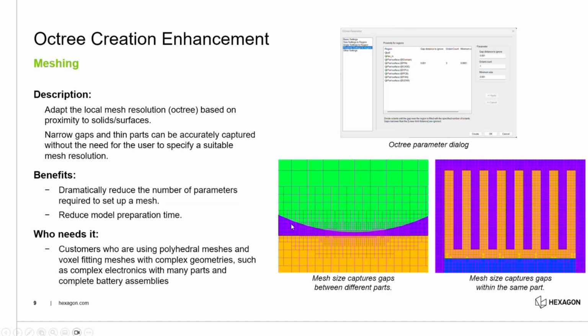The problem with this is, let's say this is typically the size of element I want to use. If I try to fit this in there, I'll maybe fit one element there, maybe not even one. So we'll end up with not enough elements through that thin section to capture the behavior at all well. So in this method, we can specify some kind of dimension, say for this kind of stuff, and refine it so that there are significantly smaller elements in that region.